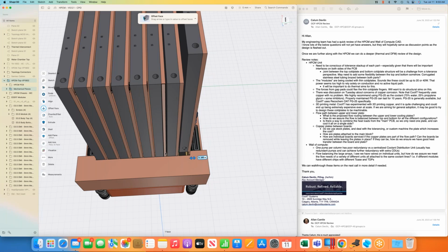So you have the lids made of copper. How about the cold plate in the back? What material are they made of? The body here, yeah, this will be the body that the SSD or memory manufacturer uses, which is typically, from what I've seen so far, a cast piece of aluminum, or a routed piece of aluminum, and they gap pad to this as well.